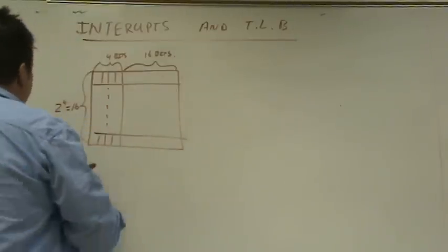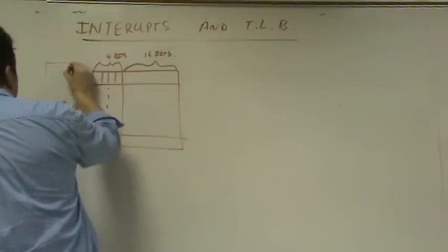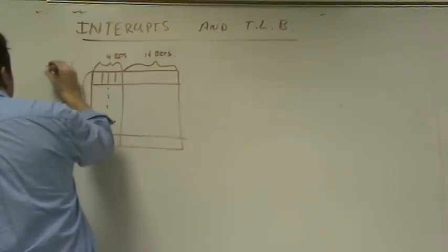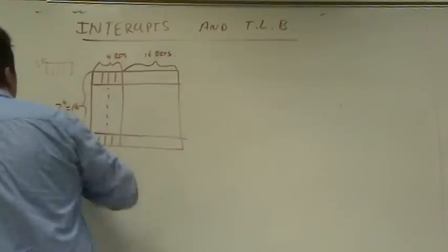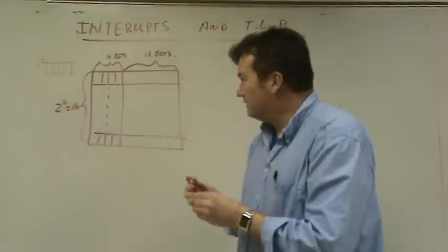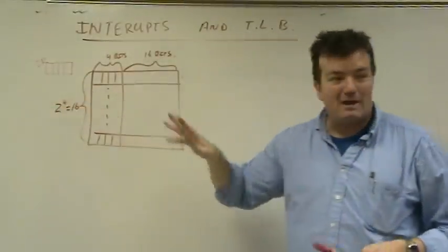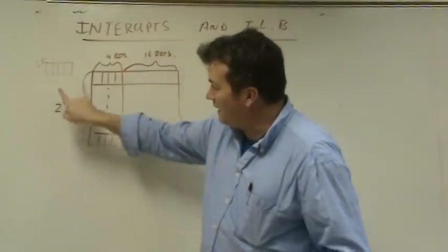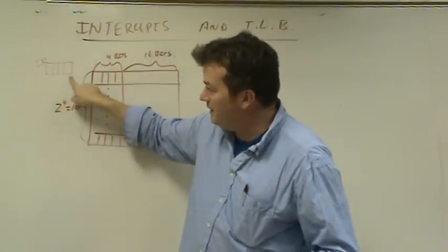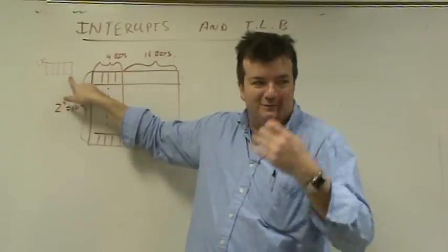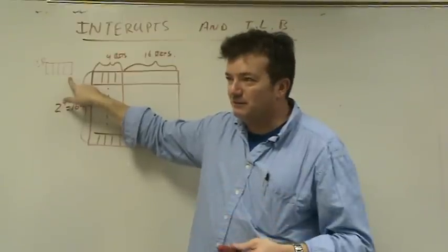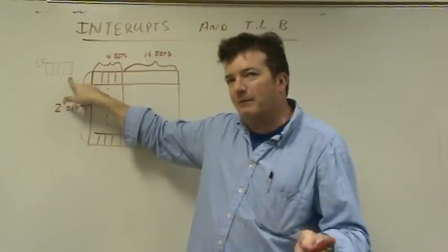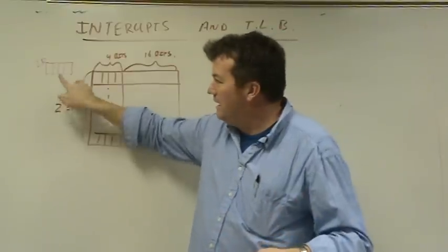And as input, we have the interrupt register, the problem that went wrong. So if we OR this whole thing together, and it turns out that power comes out, that means something's wrong. We now want to be able to say, I want to compare the number that's in here. A 3 would mean, like we made up, a 3 would mean an interrupt happened, an overflow happened, an 8 would mean divide by 0, whatever it is.